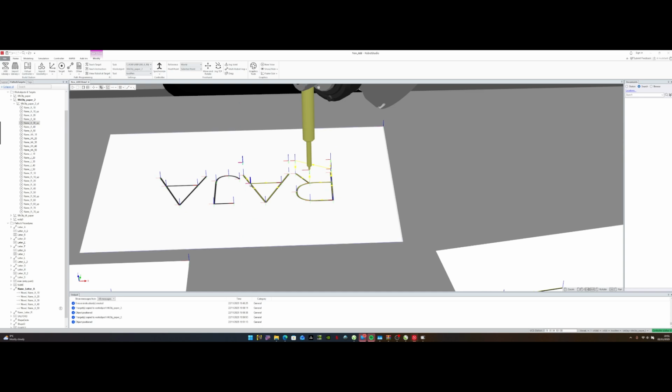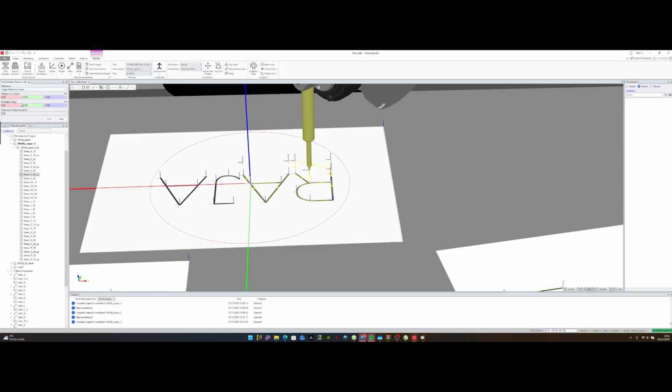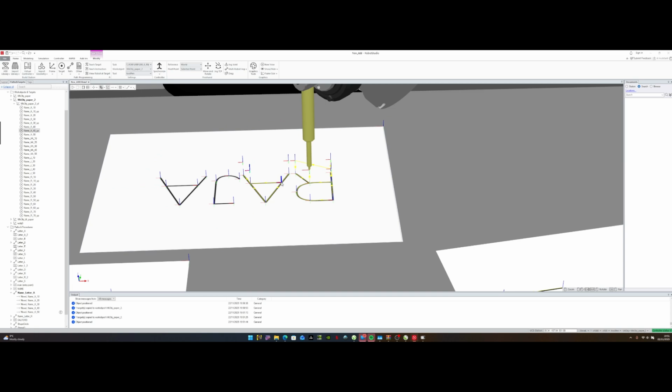Now this one, this is target 40, so we're just going to duplicate it, put up there. Then we're going to right click, modify target, set position, put target reference frame again, then we're going to set that to 15, click apply, and finally this target, duplicate first, Ctrl+C, V, now call it up.